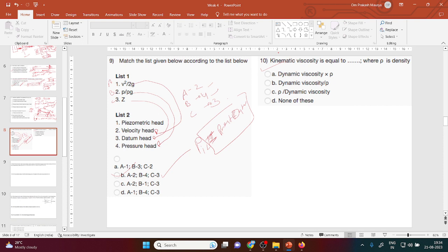What friction are you telling? Sir, if there is friction inside the pipe, it will be mainly affecting the pressure head, or it won't be affecting the velocity head. No, it will affect velocity also. Why not? You know the no slip condition, from the first lecture, right? Yes, at the wall it will be no slip. Yes, sir, continue, sir.